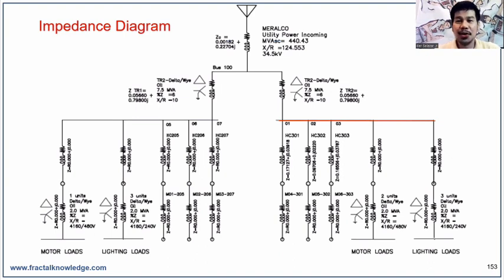With all the things that I show, the end result is simplification of impedance. With the simplification of all the electrical components, we can arrive into a very simple impedance diagram where we can use Ohm's law to solve for the short circuit current. The impedance diagram that you saw on the screen is only just a simplification of a complex electrical system, and we will reduce it further to simply find the short circuit on the red bus to an equivalent Thevenin's equivalent circuit. But we will start with residential wiring design before we go to industrial, okay?